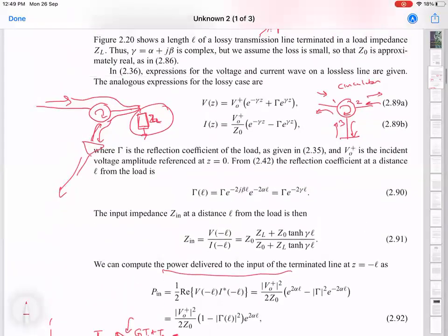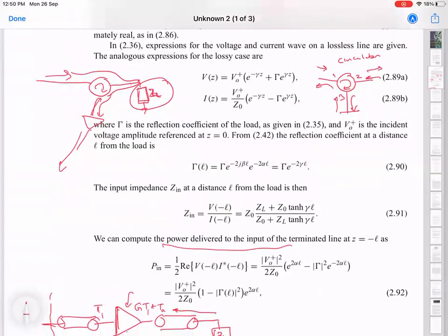So you cannot do a reflection coefficient measurement with a single path which is lossy. But the very fact also that you realize that the reflections sort of go away if you have a very lossy system. So sometimes this is used, even though it is not ideal, as a crude way of impedance matching.